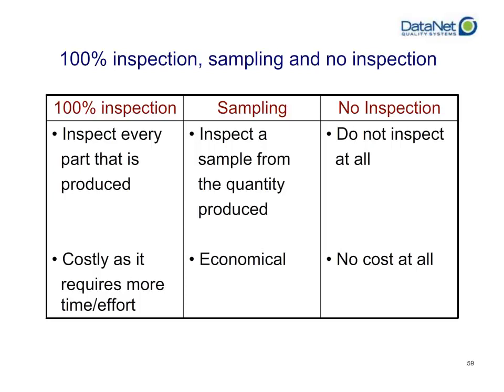The problem with 100% inspection is that it is very expensive. It requires time to measure everything. It requires effort to fix anything. It is a very expensive process. Now, in certain regulatory type situations, you may not have a choice. This is your only option. But if you're doing destructive testing, this isn't even an option at all. You can't do it, because if you have to do tensile testing and you do 100% inspection, you've literally broken everything that you are trying to sell or produce.